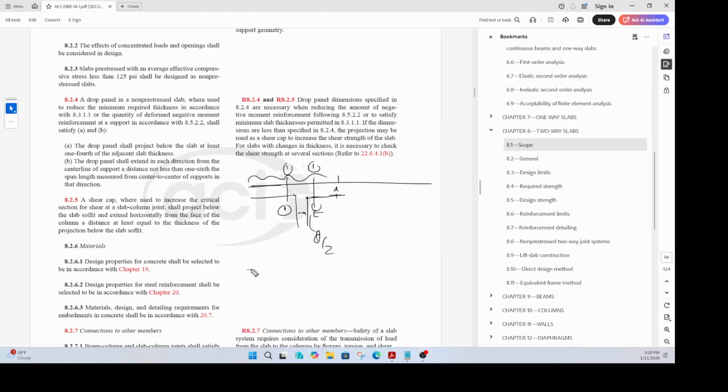So in plan view, let's say here is the slab, and that is your column, right? This column edge lines up with that edge. The critical section might be that much, and let us say that the load is acting on this area. This is the tributary area, and the entire area, so let's say that is A, times your qu, the factored load acting on it. That is the shear force, and the force is resisted by this area here, right? This is the perimeter. So let's say b, b, b, and b. So add all those four, and you get a perimeter.